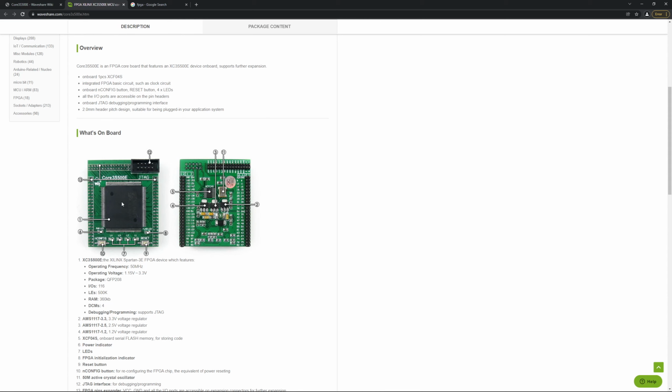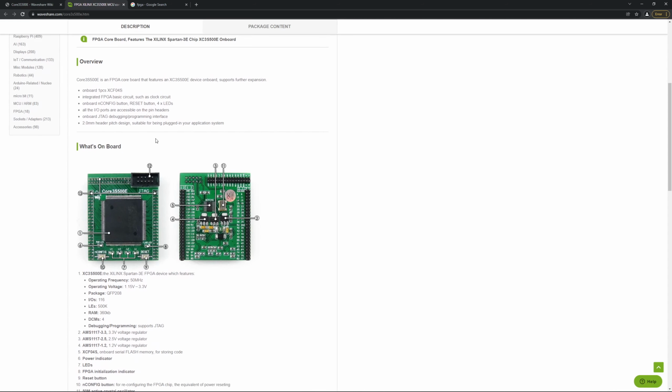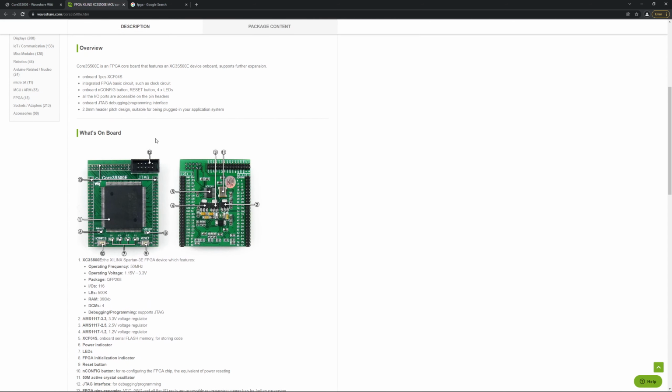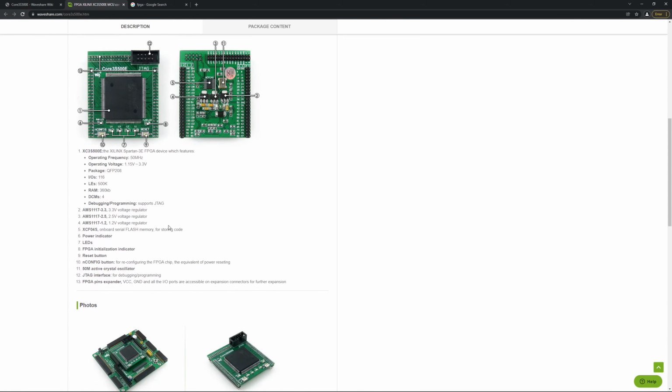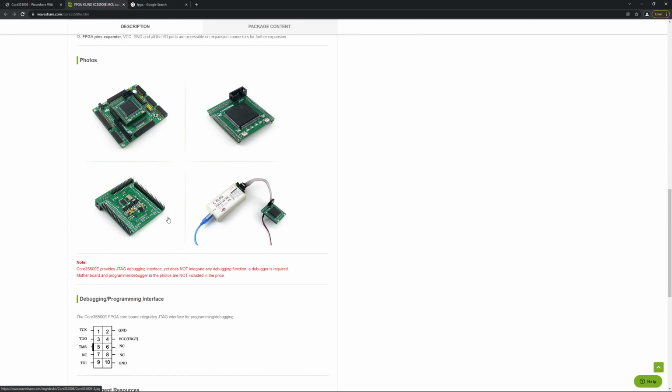There's no processing overhead. It doesn't have any kind of microcontroller or processor on there. It just has a whole bunch of arrays of logic elements, which are basically lookup tables that are configurable to implement whatever logic function you need. And you can configure them and have your circuit running on this thing in real time. It's a very interesting concept.